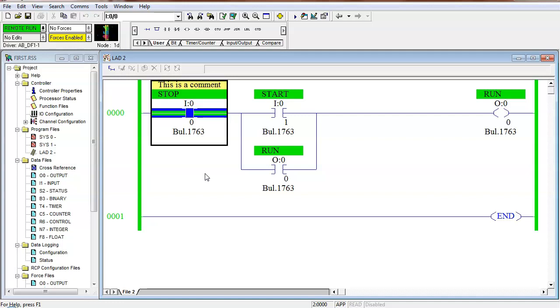When we're dealing with inputs, that is not a normally open or normally closed contact. One of them is true if it's open. The other one is true if it's closed. So this is true if it's closed, right? And the other one is true when it's what? When it's open. That's what the examine if open and examine if closed are. So if you run into a diagram in the book and it calls that thing a stop, then you need to use an examine if closed instruction.